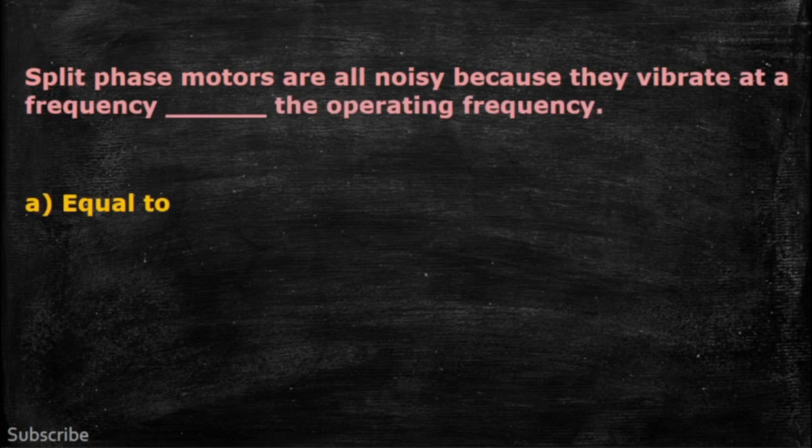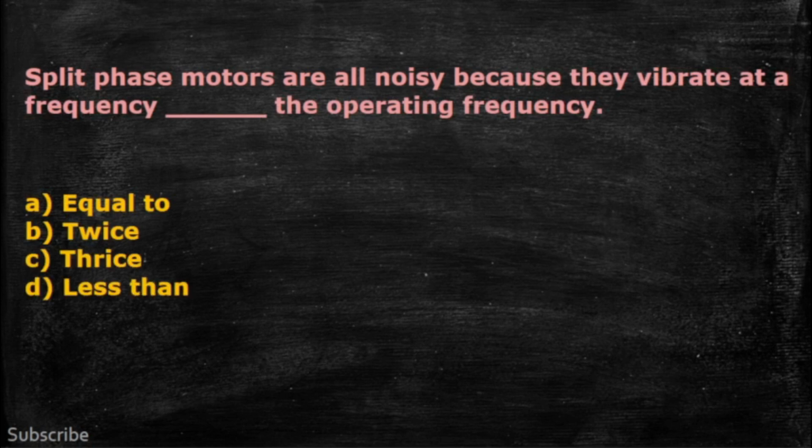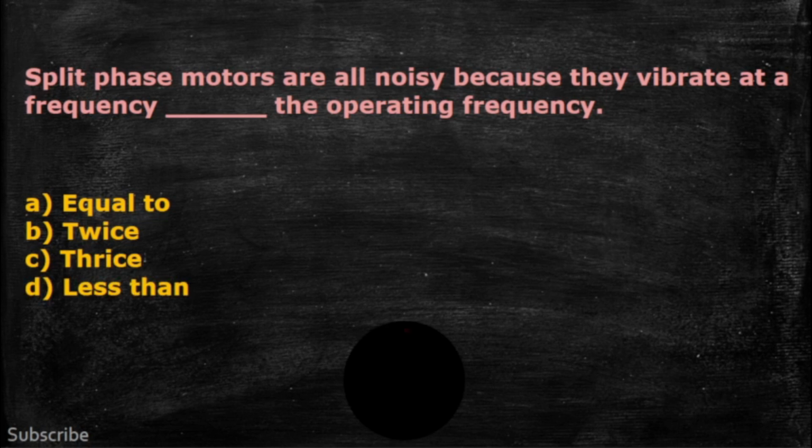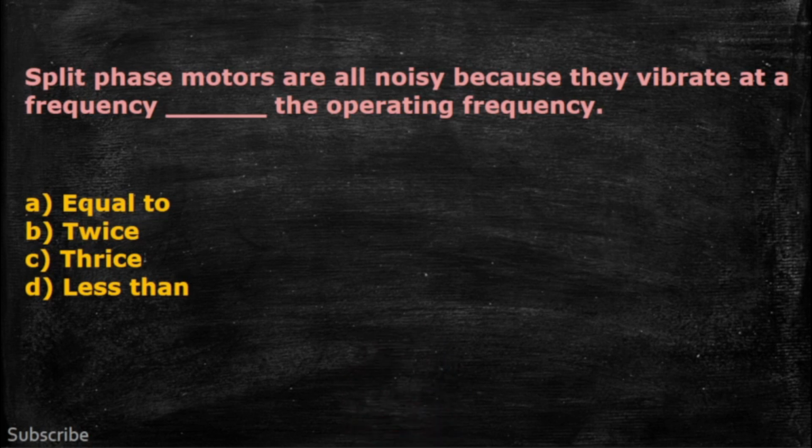Question number 5. Split-phase motors are all noisy because they vibrate at a frequency blank the operating frequency. A. Equal to. B. Twice. C. Thrice. D. Less than. The correct answer is letter B. Twice.